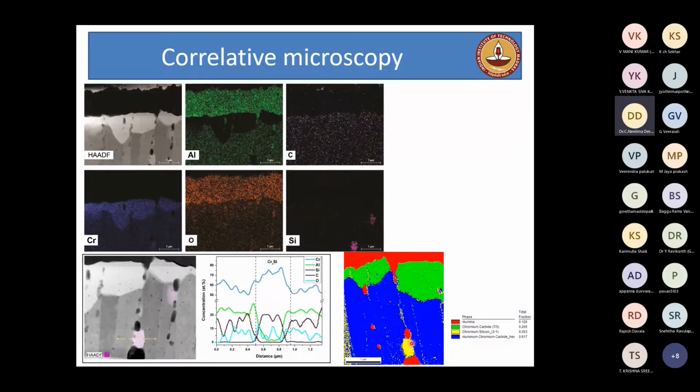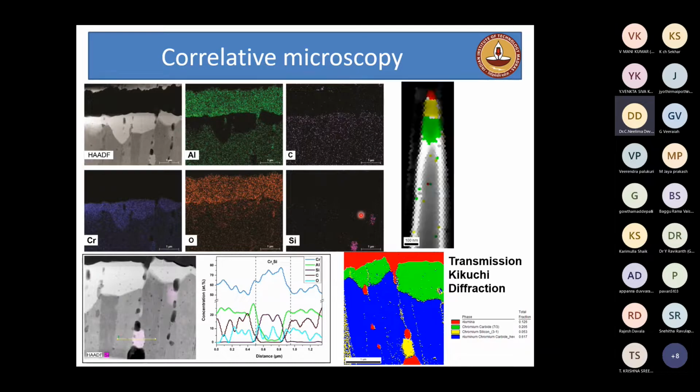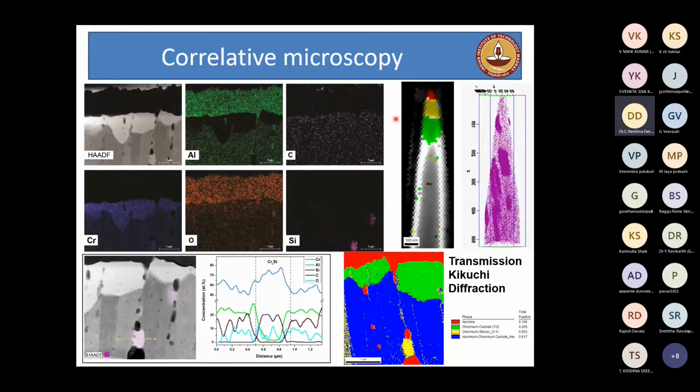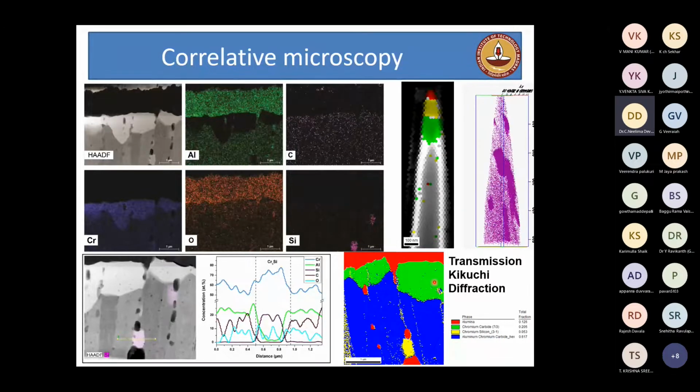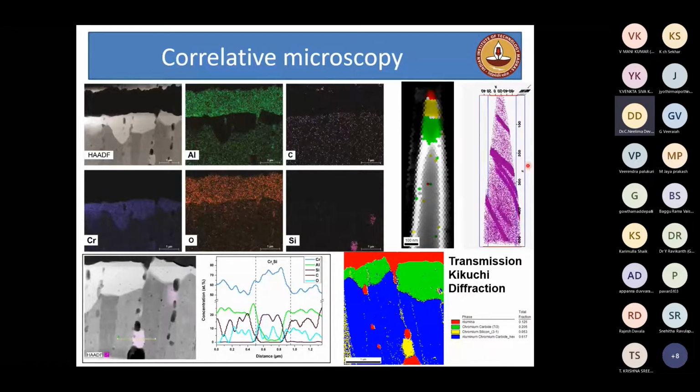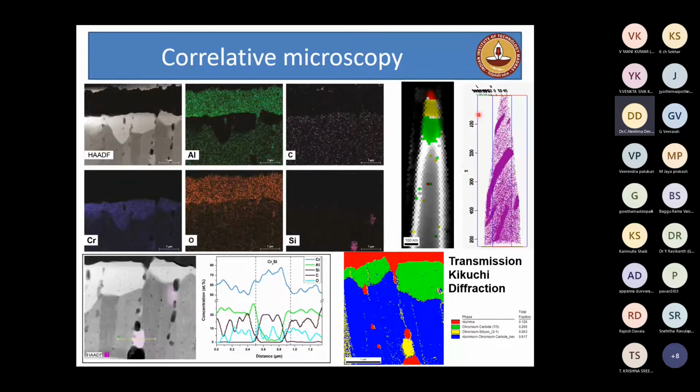So you get the crystallography, you get the chemistry, you get the location identification. Now you can take it to atom probe tomography at the nanometer scale, do a similar type of mapping, and see that there are 3 different regions present inside. If you take the tip to the atom probe, then you can see the silicon enrichment nicely visualized. That means you can correlate one-to-one in an ex situ method, but you can also correlate in a direct method, where the needle itself is looked at for crystallography and for chemistry by atom probe.